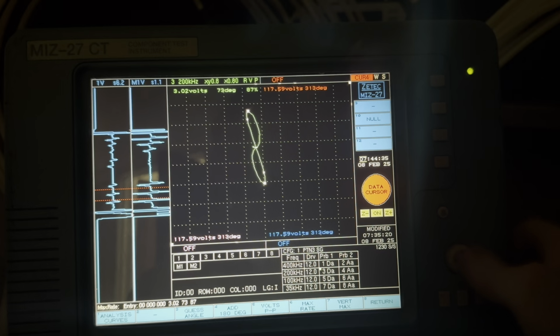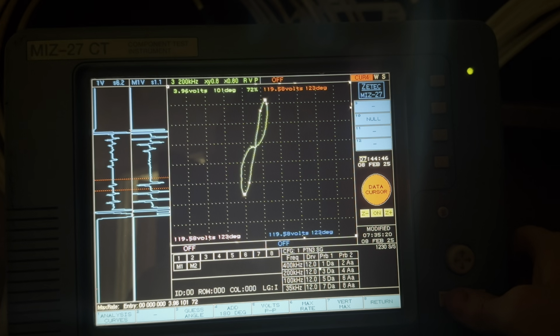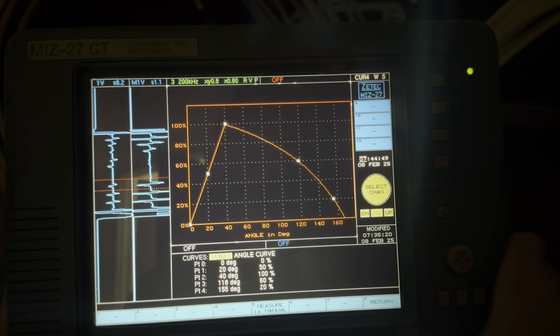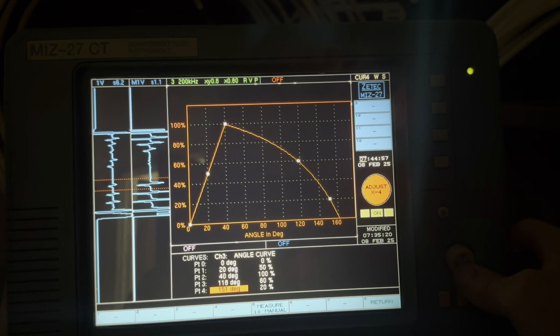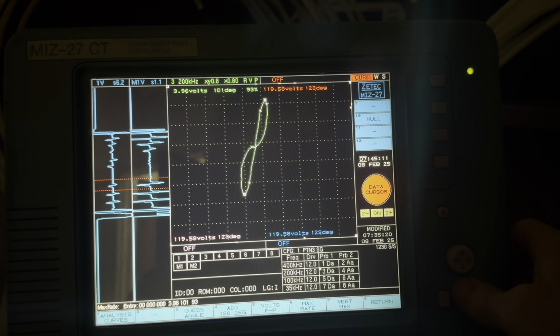I'm going to go back to the data. I'm going to rotate to navigate to the signal from the 20% flat bottom holes. I'm going to measure that using max rate. That's 120 degrees. So go to the analysis curve. I'll go down to here. Okay, I can already see I screwed something up here. That's 120, we said. Now this curve's going to come out all jacked up because I messed up on the angle of the 60. So I'm going to watch this.